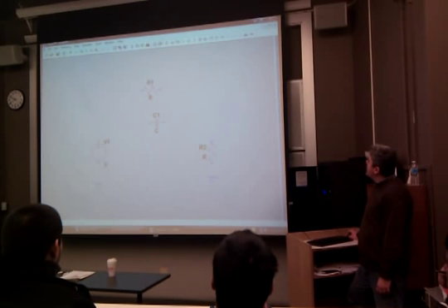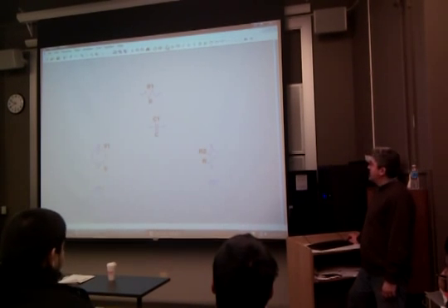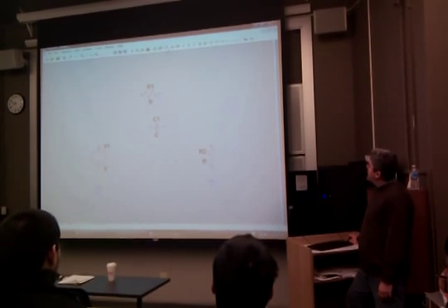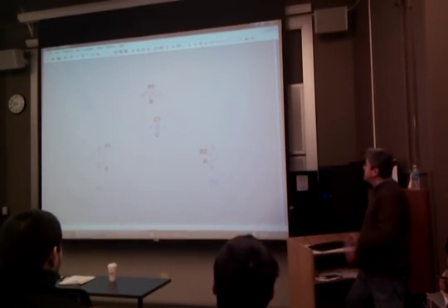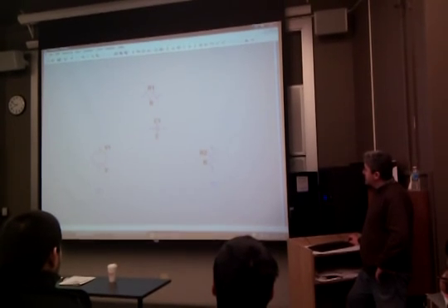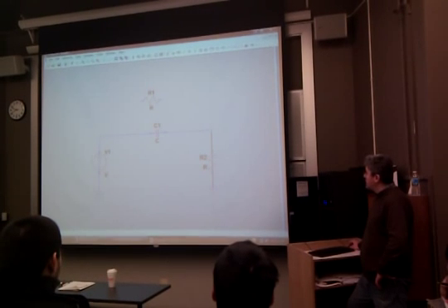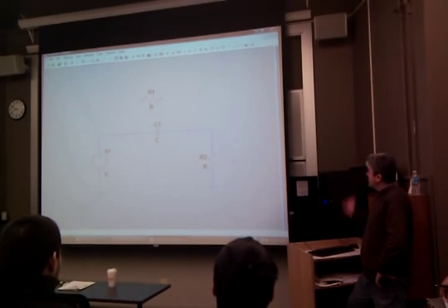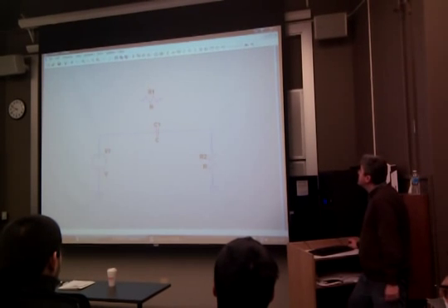Okay. So the wiring is kind of nice because it allows you to do quick wiring, as it's called. So I can click on this to do the wiring, connect the components, or I can press F3. Same thing. And I can just go through the components actually. And it won't short them out. LTspice will short them out. Don't try this at home with LTspice. You'll get shorts. But I can just do this and then right click, they're connected. You see? And then F3 again if you want. That F3? F3, yes.